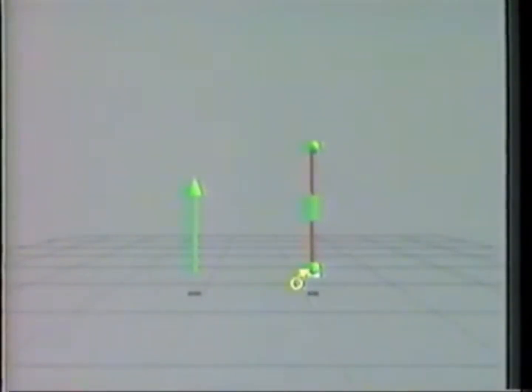length widget. The shape of the cursor indicates that we are selecting the from object. When the endpoint is selected, it highlights purple, and the cursor changes to indicate that we can now select the to object. Note that objects only highlight purple when being linked together with constraints. We then select the ray, and it too turns purple. Now the cursor indicates that the system is waiting for user confirmation. We click again with the mouse to confirm this constraint.